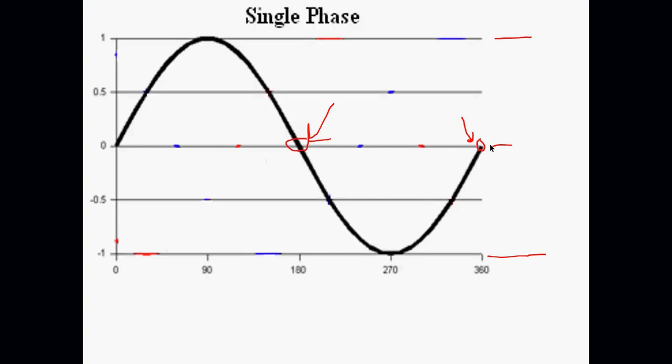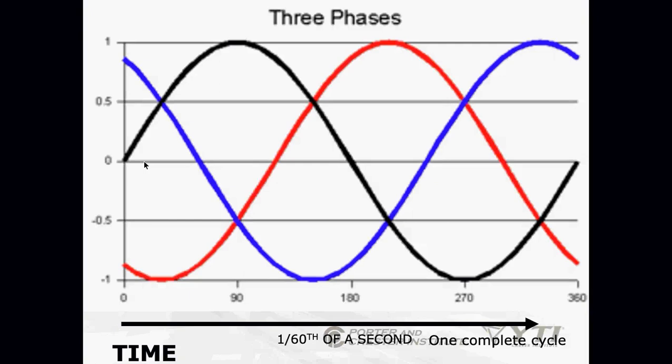Our motors lose efficiency. Yes, I can use a start cap, or I can use a start winding to slightly give me another phase, but it's not as reliable as having a true three-phase circuit.